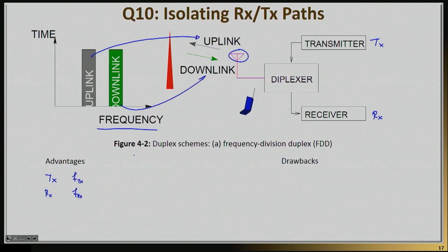Probably the biggest drawback is leakage. What I mean by leakage is the following. So this transmitter is basically transmitting now, and you're also trying to receive now. The only difference is that there are two different frequencies, two different channels. But how much are they transmitting?